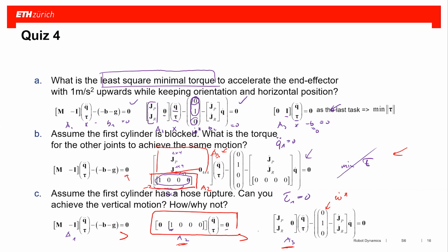Why are A1 and A2 not the same priority? We can put them at exactly the same priority. This is no problem. The motion constraints and the dynamics equations of motion can be at the same priority. And in fact, if you're very sure that, independent of what you're doing, the constraints and certain tasks can be assembled into one task with the same priority and it will not change your solution, then I would do it just because of numerical efficiency of the whole setup. But overall, it doesn't really matter too much if you have a clever optimization pipeline in the backend. This will do this for you.